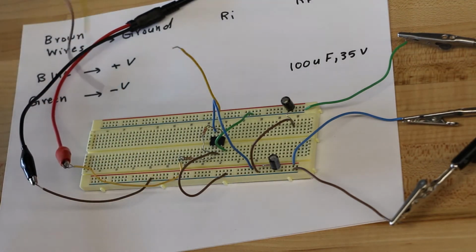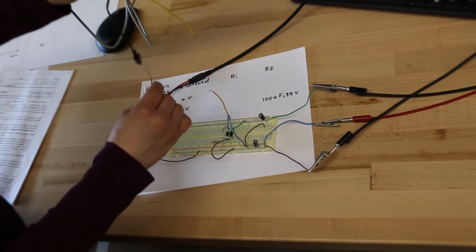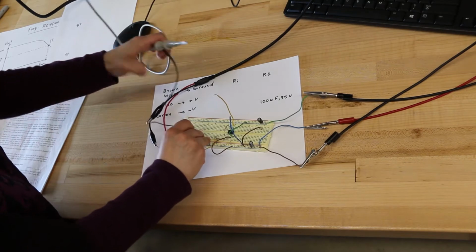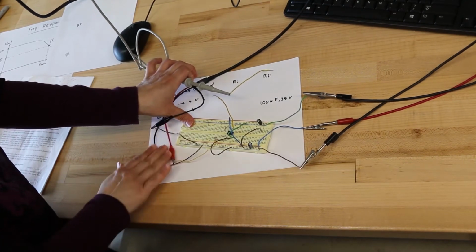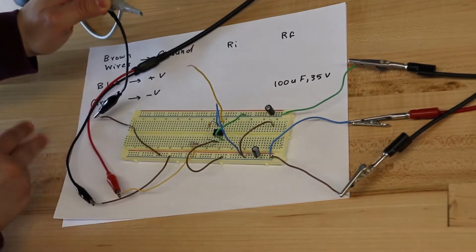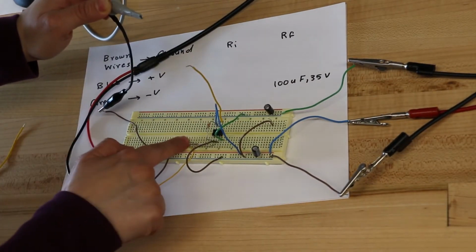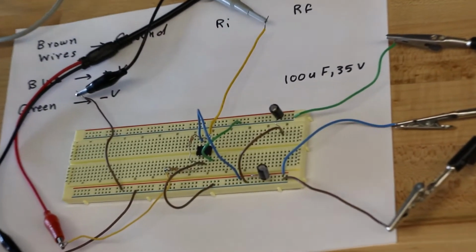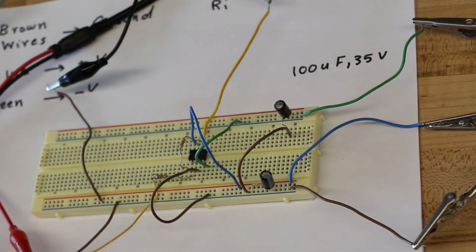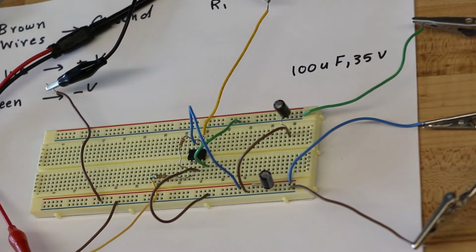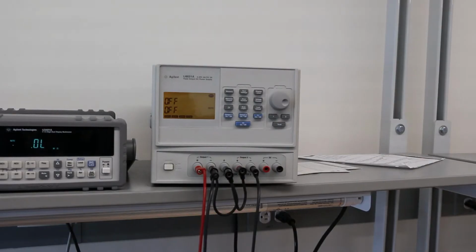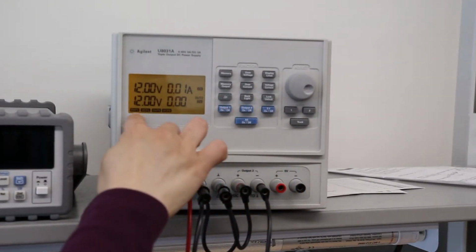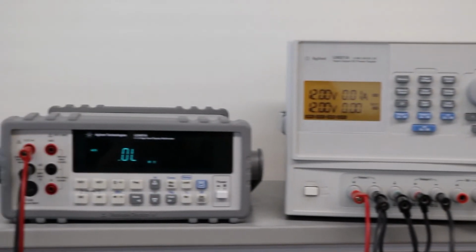This is the probe that's connected to channel number 2. This is the ground. And this should be connected to the output of the circuit. And the output of the op-amp is pin number 6. Now the circuit is ready to apply the power. So this is to apply the power. Channel 1 gives 12 volts, channel 2 too, and then apply signal to the input.